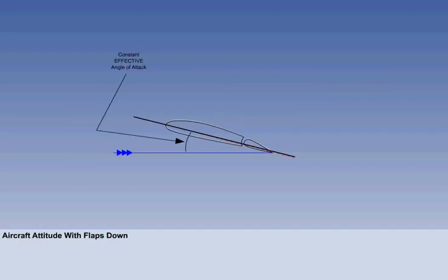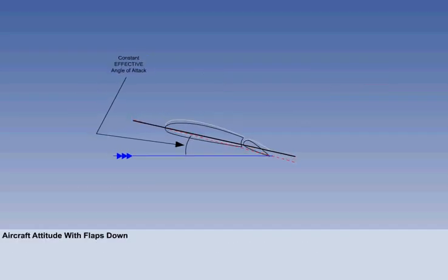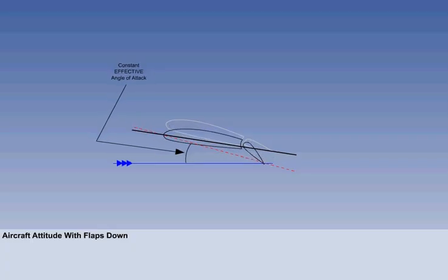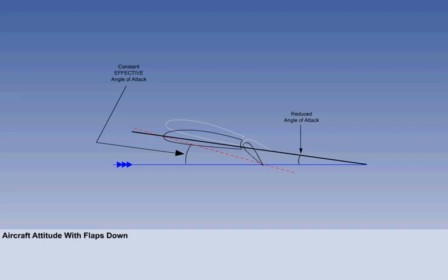This animation repeats the fact that as flaps are lowered, the pilot must decrease the angle of attack, so that lift remains the same as the weight. Therefore, with flaps down, the aircraft will fly in a more nose-down attitude. On approach to landing, this is an advantage, as it gives a better view of the runway.